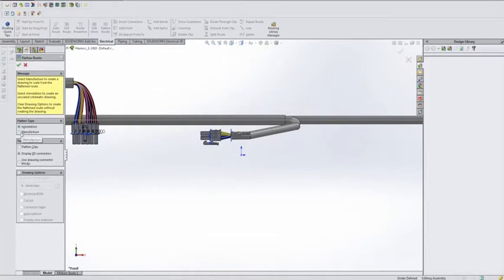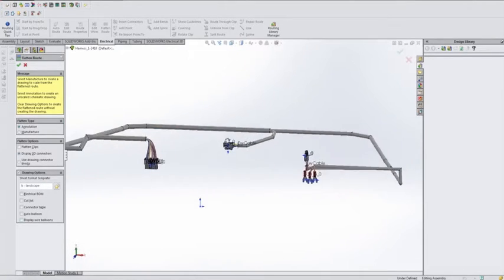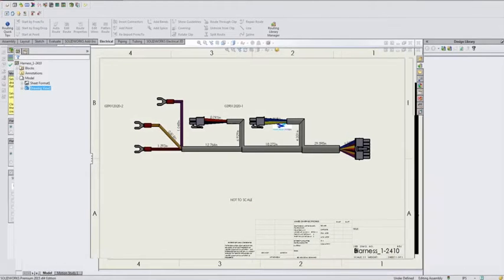And then I'll go ahead and select here for annotation and manufacture. Now, if you're doing something more like a nail board, then you'll go ahead and choose manufacture. But in this case, we're going to go ahead and do an annotation drawing. I'll do all my connectors, right? And I'll have this create a drawing for me. I'm going to have none of these connector tables, don't need them now, but indicate that I do want some B landscape. I'm also going to indicate my length here. This is going to pretty much predefine what's going to be my center, what it's going to be drawn around. Serve as my center point for my drawing, for instance. Pressing OK. It'll then create my annotation drawing.